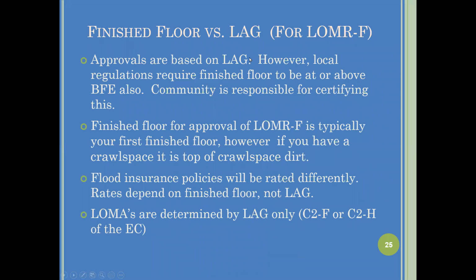Here's a little information about the finished floor versus the lowest adjacent grade. Approvals for LOMR-Fs are based on the lowest adjacent grade. However, local regulations require finished floor to be at or above the base flood elevation also, and the community is responsible for certifying this.